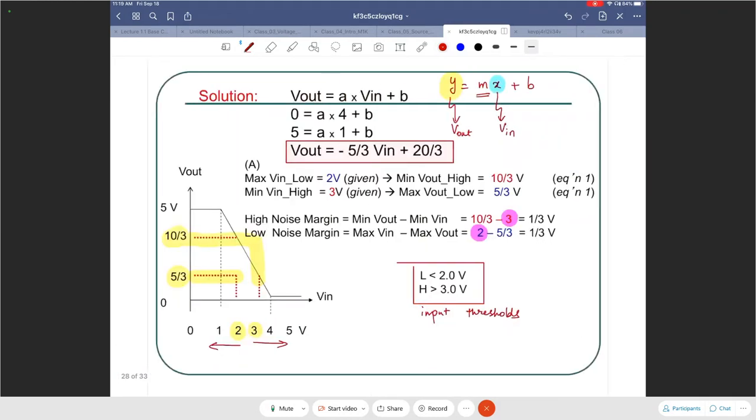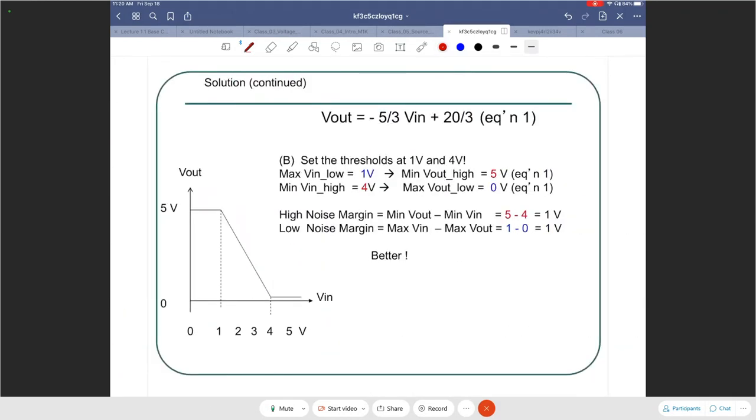And hence we made it better, right? Questions about this? How are we doing? Noise margin is a simple subtraction operation. I need 4 points. Given the input-output characteristic and 2 thresholds, I can find the 4 values I need to perform the subtraction for the high level and for the low level. Low noise margin is bad because that means lower tolerance to noise. High noise margin is better because that means higher tolerance to noise. Noise itself, you want as little as possible in your system.